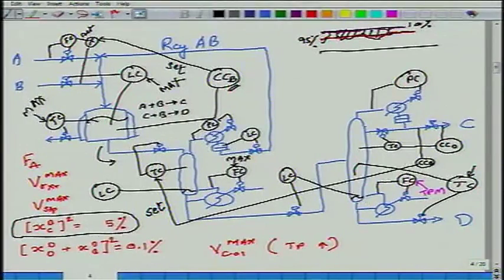Can you adjust something that indirectly adjusts the feed? Absolutely. There you go. Limiting reactant was 5%. Now I start jacking up its composition from 5% to 6%, 7%, 8%, 9%, 10%. More limiting reactant going in. You see the composition controller will adjust the ratio. If you adjust the ratio, you can always adjust the ratio in a manner so that more B gets sucked in.